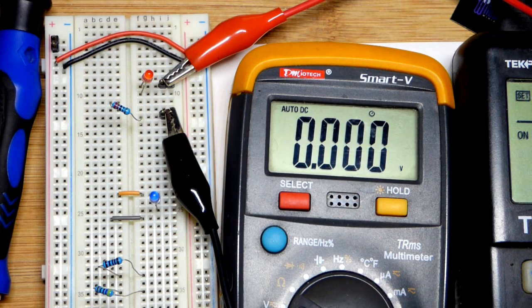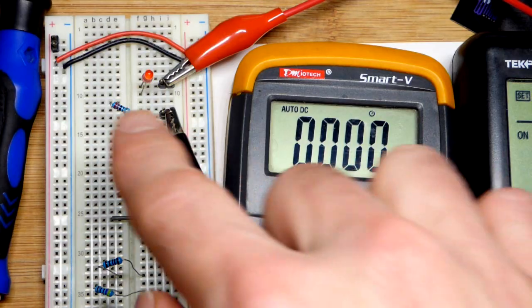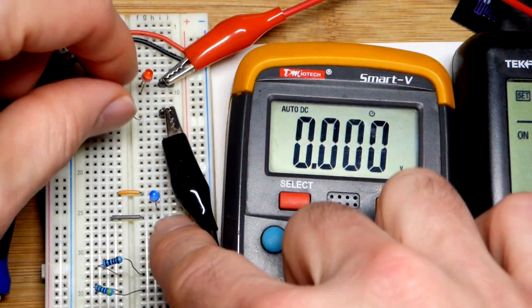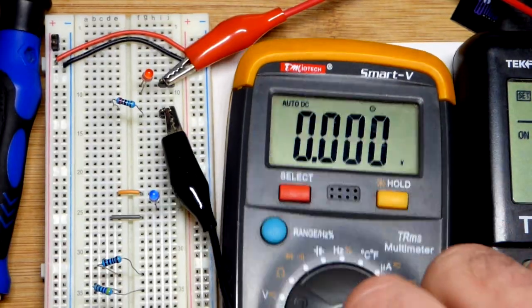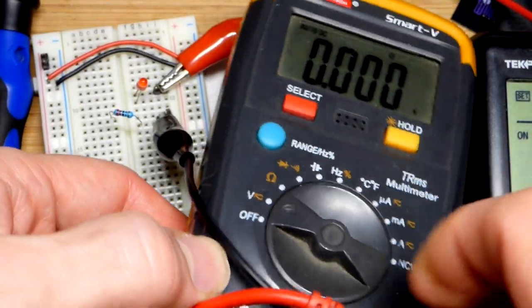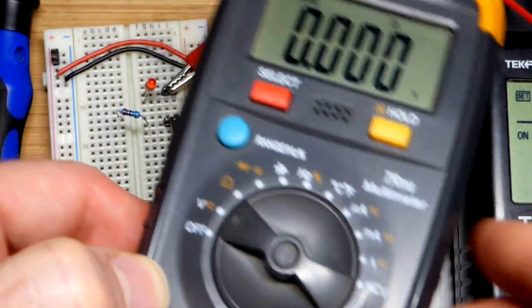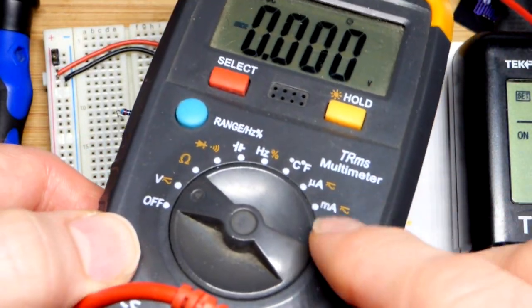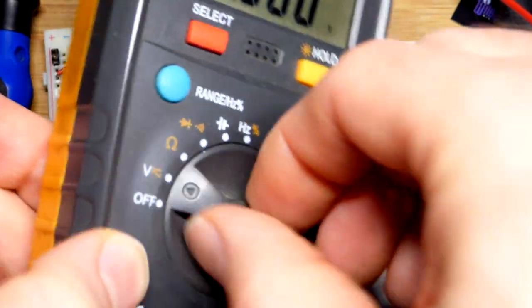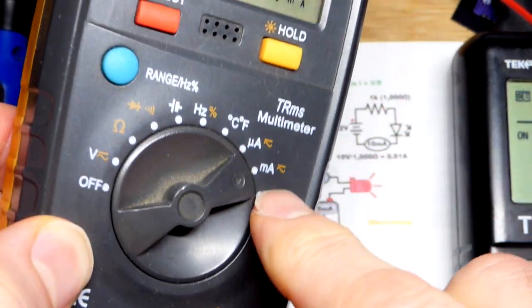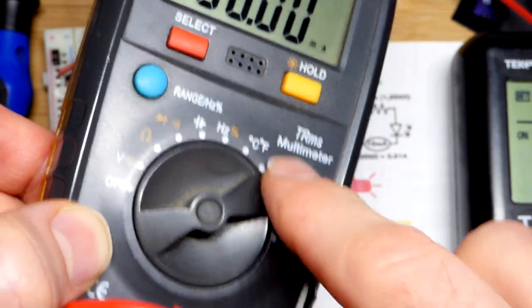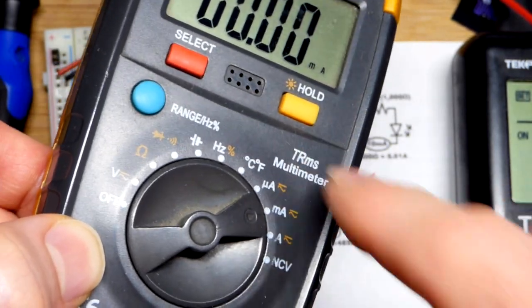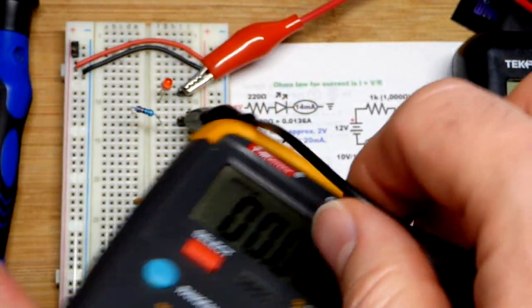So we have the meter set to voltage. We opened up the circuit, so there's a gap right now, and we are going to take the meter. And again, I don't have to move the probe for anything other than high current. That wire is going to be kind of annoying. But we're going to measure in milliamps right there. So this one's really important. If it has numbers next to the amps right there, milliamps, whatever, make sure you set it to a number higher than you can expect to measure.